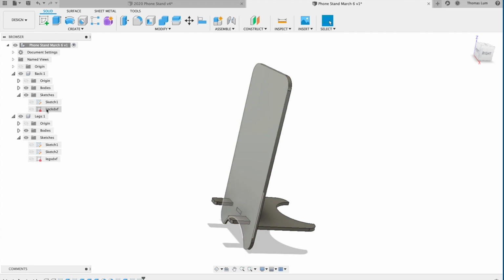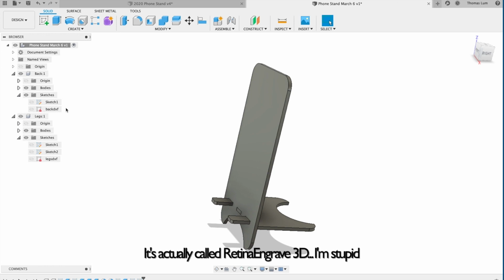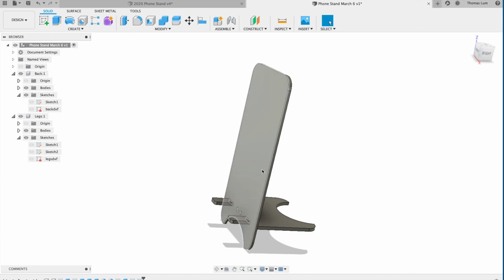So these DXF files, this is what you take into the laser cutter. It has its own little program. You actually have to print technically to it. So we open these up in Inkscape, or if you have Illustrator, you use it in there, and you actually go from there. You just click print, and it sends it to the laser cutter essentially through a program called Full Spectrum Laser, because that's the name of the company as well. So it just sends it from basically like MS Word. You just send it to the printer, in this case the laser cutter, and then the laser cutter goes from there and cuts these shapes out.